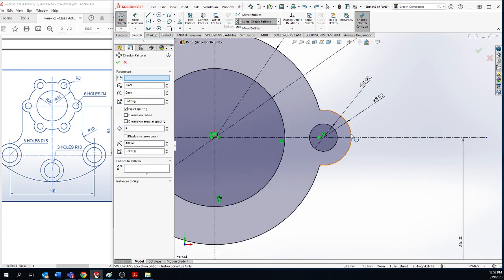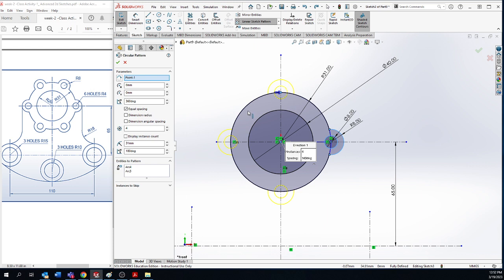The pattern should be repeated. So click on this arc and this inner circle. You can see now there are 4 elements copied. See, by default it is showing 4 here. So that is why we are able to see 4, and the required pattern is 6. So change 4 to 6, enter. Then they did not specify anything about the spacing between one pattern and the other pattern.